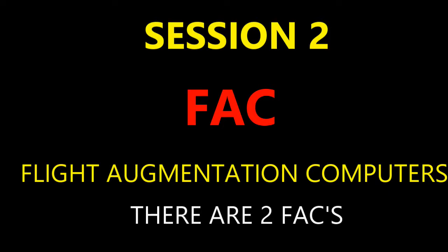Then you also have a minimum selectable speed. There are different little abbreviations for these different terms, but I'm not going to go into those. Just know that the top of an amber strip along the speed scale is the minimum selectable speed, and of course it's computed by the FACs. So with the speed scale, I just wanted you to get the idea of how the numbering goes, and the yellow indicator, and also the identification through color, with that cyan magenta color for target airspeed.